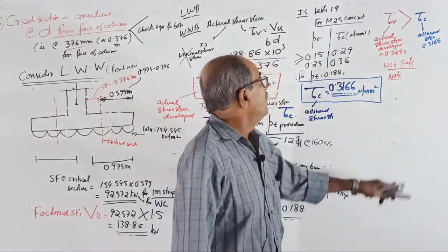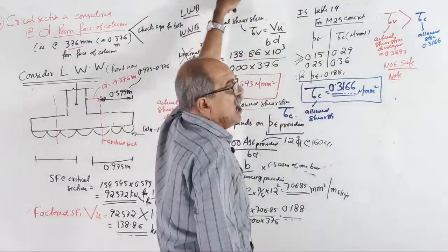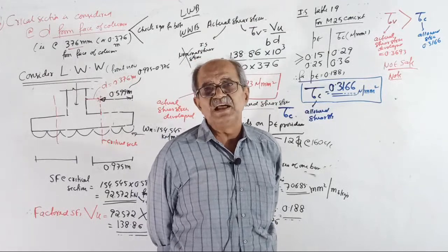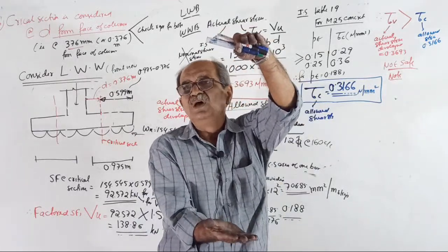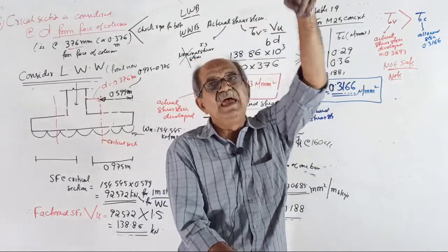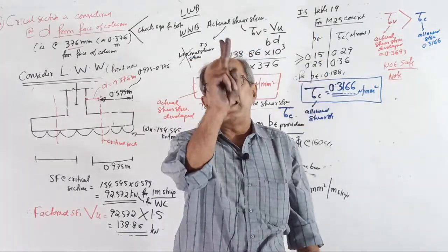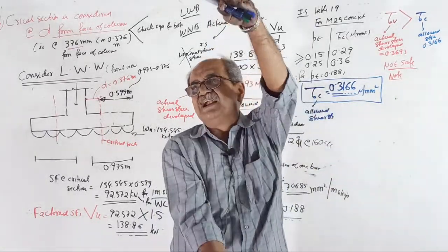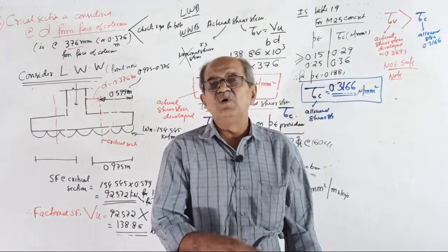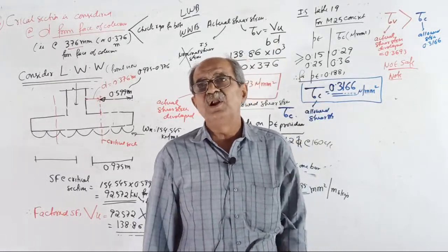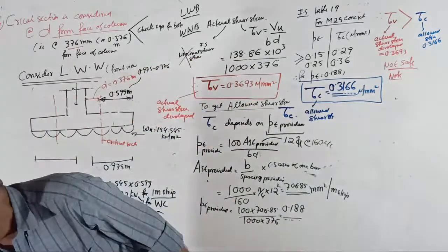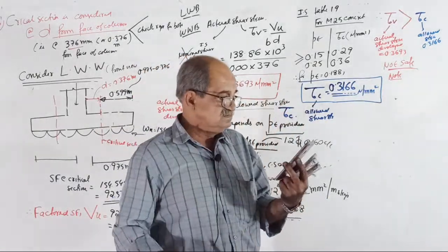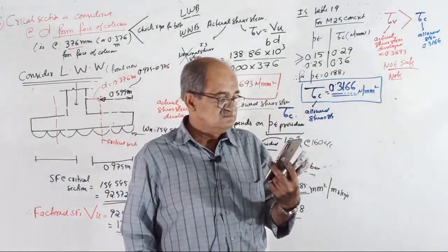Practically, for this footing, not 450, I think people will take around 550 or 600 mm depth, 2 feet. Clear now? For this column, 850 kN load, they will tell 2 feet. They will tell, give a depth of 600, not 450, 1.5 feet, that is around 18 inches. No, they will tell 24 inches. Clear now? I took it lesser only to show you that unsafe will come. Clear or not? This concept.